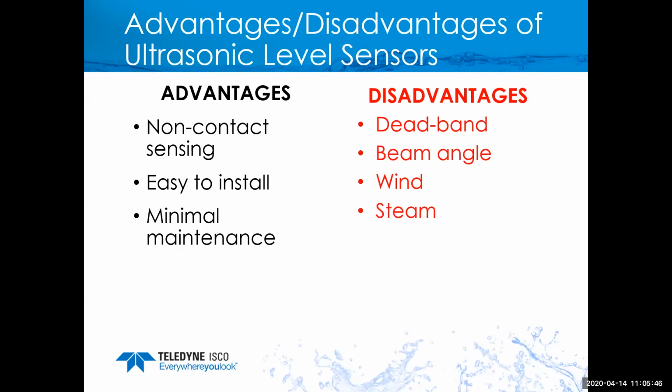because the ultrasonic sensor will reflect off of the water particles in the air, which could then give you an incorrect level reading or reduced signal strength. Foam can also be a problem because it will minimize the ultrasonic signal strength, and it may actually absorb the ultrasonic sound wave, thus giving you an error.